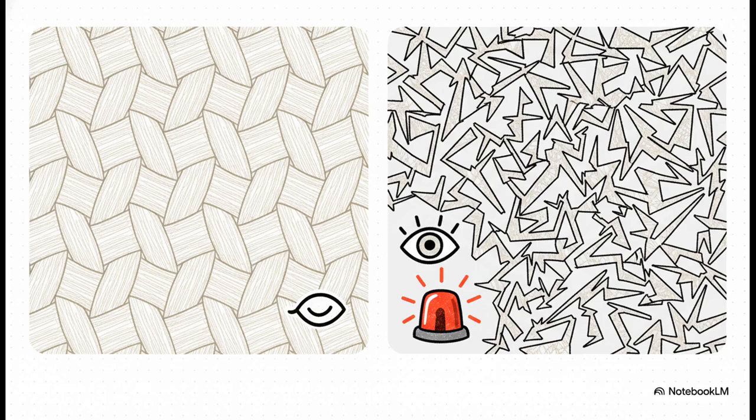Normal machine sounds produce regular, periodic patterns that look like natural textures, again, like wood grain or fabric, which the ImageNet AI has seen millions of times. But mechanical faults, they create non-linear spectral patterns. When those get translated into our RGB sound frame, they turn into weird, irregular visual textures. The visual AI instantly flags these as bizarre, out-of-distribution patches.